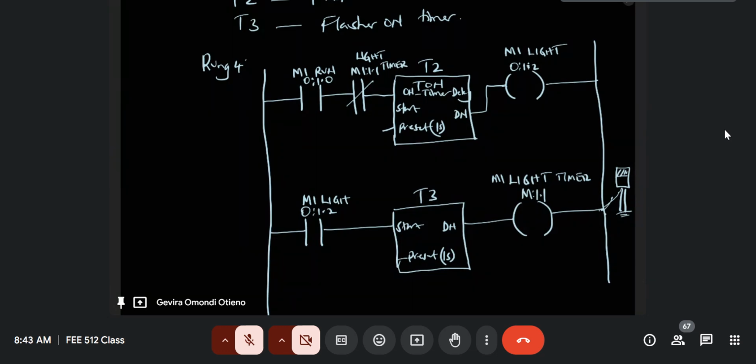So let's look at how it works now. Let's see, the motor has started running in rank 3 based on the conditions that have been provided. We are just following the sequence, the scan cycle. So we have a logic true here. Let's see if it will make sense now. Remember, there is nothing here. So let's say at this state it is false because there's nothing. The timer T3 is not working yet. It's just been connected. It's not running, so it's false at that state.